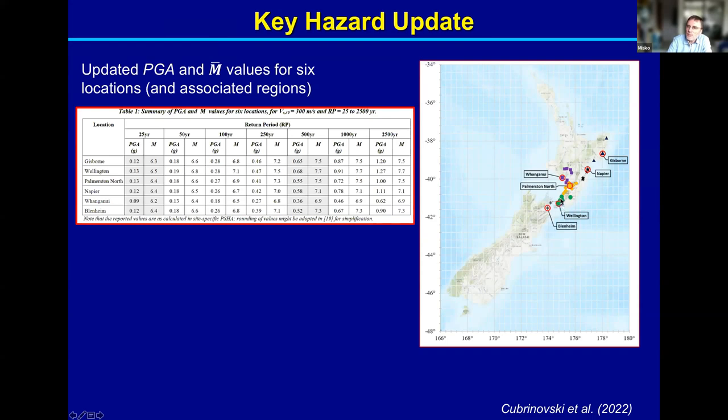And the other green points here indicate surrounding areas which have similar hazard based on NZTA interpretation and based on NZS 1170 interpretation. In other words, in NZS 1170, all green symbols are having similar hazard. Since we did calculate only for Wellington here, then we adopted the same hazard for the respective areas, as I said, based on both Bridge Manual and NZS 1170.